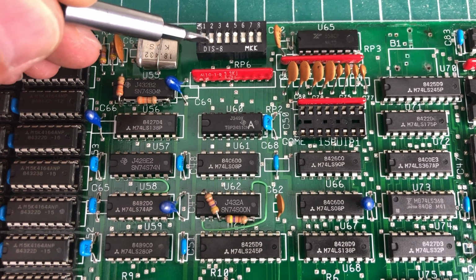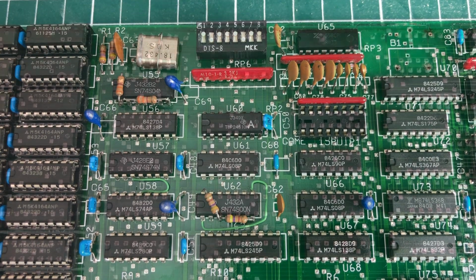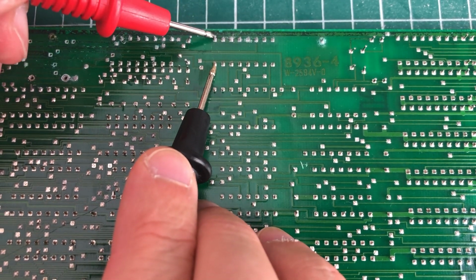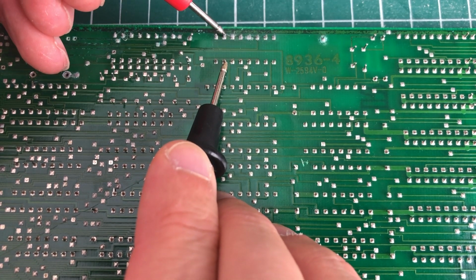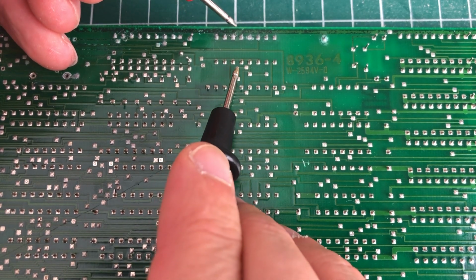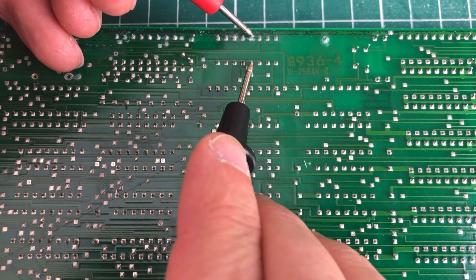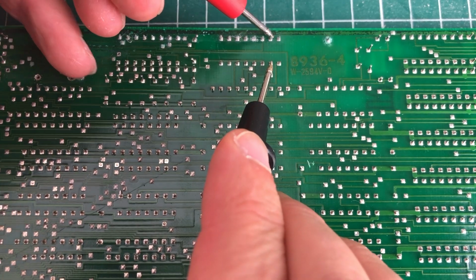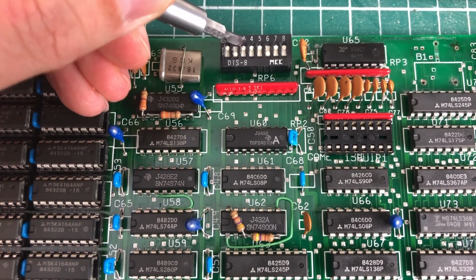Now, all of the dip switches were set in the correct position, but I did notice that it was kind of hard to switch them. And I also noticed that although some dip switches were in the on position, meaning that they should provide continuity between the 2 pins here, some dip switches which were in the on position did not provide continuity. And importantly, the dip switch for enabling the memory didn't provide any continuity. So that was probably the reason why it did not find the card.